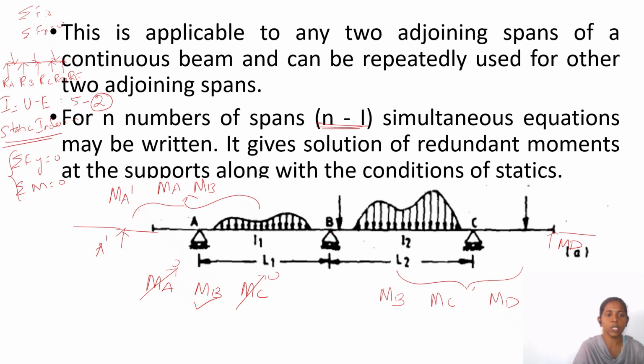If there is any inclined load, then summation of Fx, Fy and moment all equal to 0 apply. Here, 5 reactions are unknown and 2 equations are available, so totally 3 indeterminacies are to be solved.